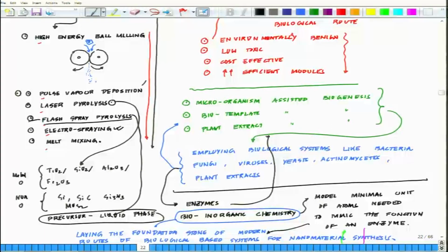So, the last of this lot is melt mixing. Melt mixing is essentially a method involved mechanical mixing of a polymer with modified nanofillers by extrusion or kneading, and less commonly by injection molding techniques. Okay. This is one of the oldest methods to design polymer composites with nanoparticles.